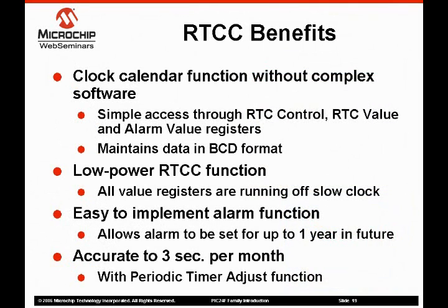Now for a quick review of the RTCC, we'll take a look at how the RTCC can benefit a designer. First, the RTCC creates a very easy-to-use clock function. Once set, there is no need for software to calculate the time, date, month, year, or to adjust for a leap year. This eliminates most of the software involved in implementing a real-time clock calendar in software. Your software interfaces with a few configuration and value registers to set and read data. All the values are stored in BCD, providing the data in the format you're most likely to need it in. The registers are maintained by the RTCC in a low-speed clock domain, making the peripheral very low power.